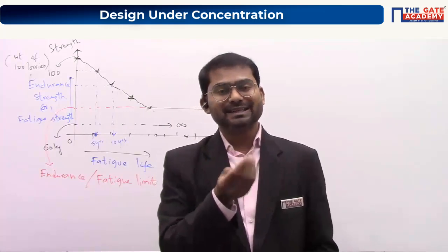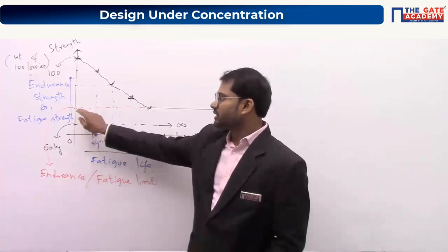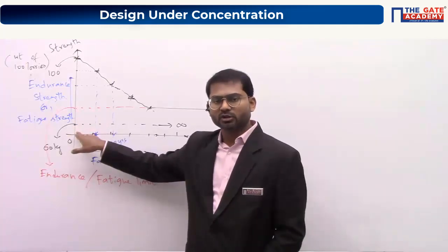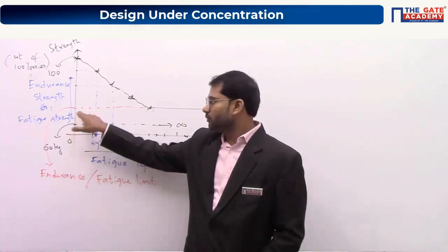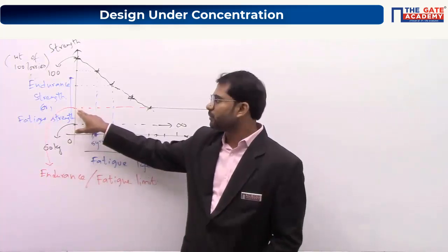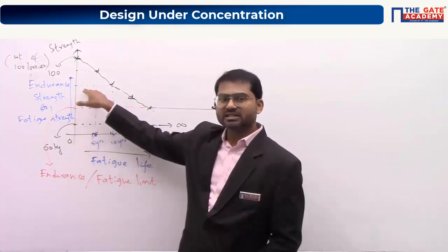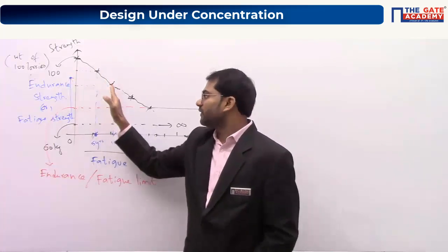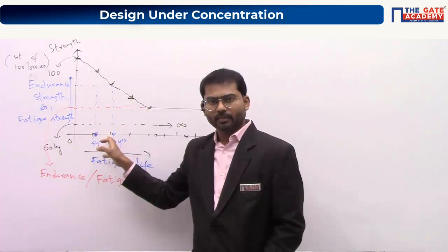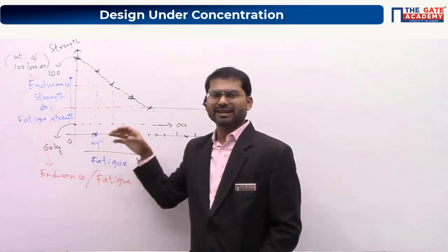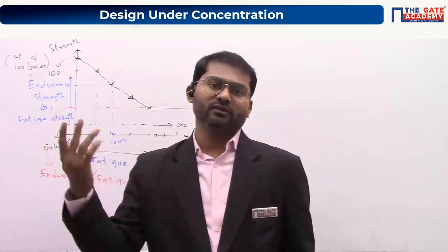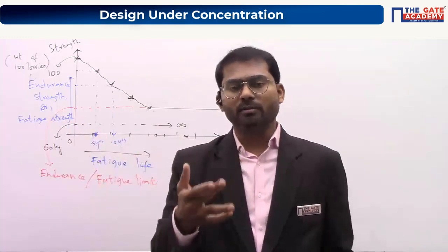That means the endurance limit value is that small, and you should not go beyond that value. But in most cases we will be applying loads which are above this. That's the reason why any component which is experiencing dynamic loads will be failing after some point of time. Understand? So very, very rarely do we see a component is there forever, unless it is a monument like the Taj Mahal, etc.